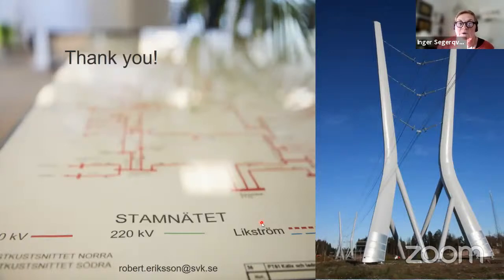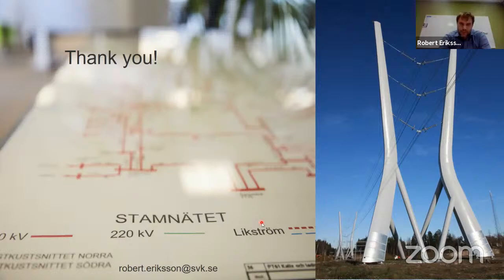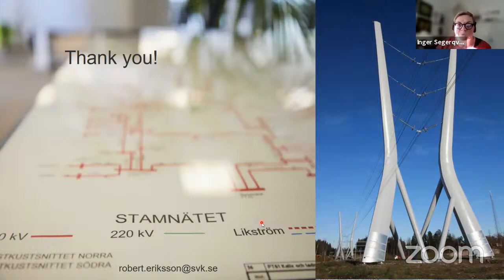And then there's finally one question about experience in the Nordic regarding loss of an HVDC link, if there has already been some experience in that for overfrequency. Yeah, we had a trip of an HVDC link like 1 year ago during commissioning. It was actually first over frequency, and then it went back and was transferring power in the other direction. So first we had over frequency, then we had under frequency within just 1 minute or so. So it has happened.